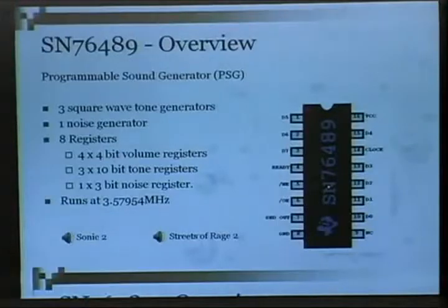It stands for Programmable Sound Generator. It's an integrated circuit with everything you need in it. It has an audio mixer, has a built-in oscillator, so all you need to do to get data out of it is write to each of the pins. So how do you do that?